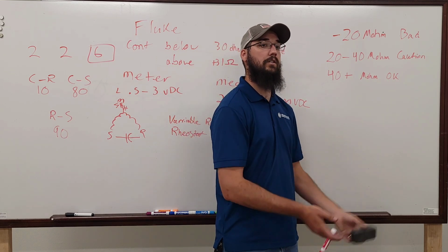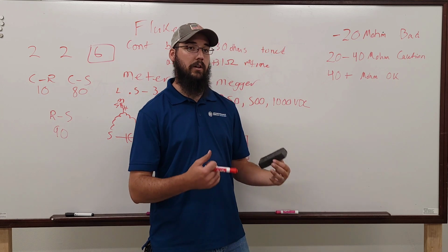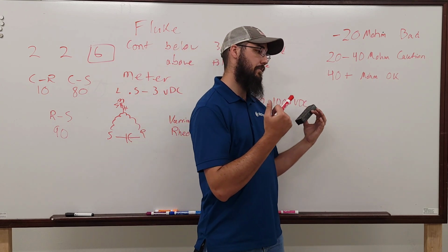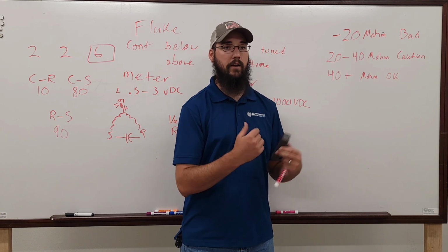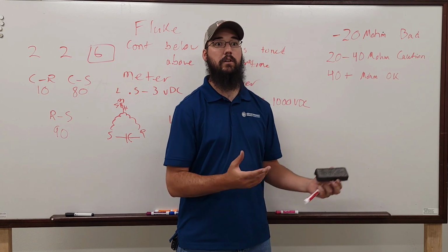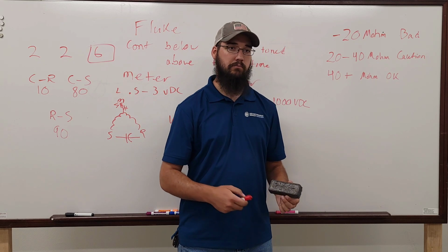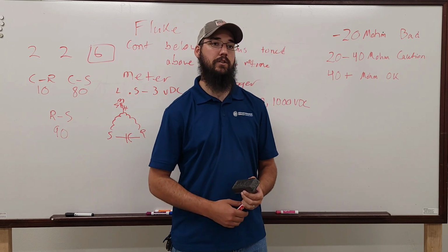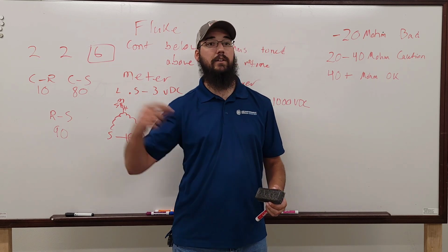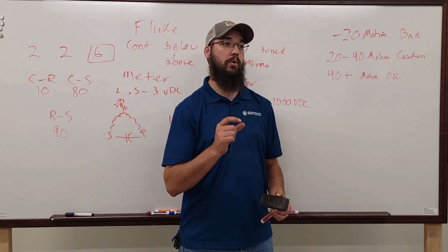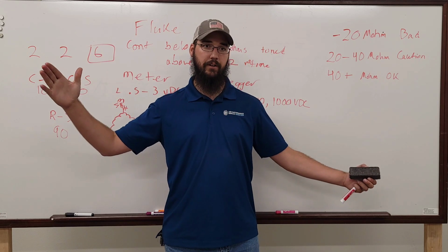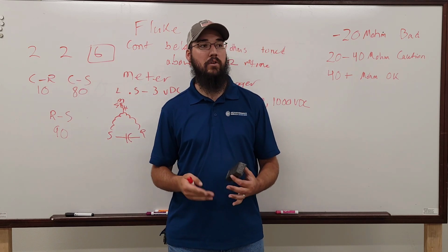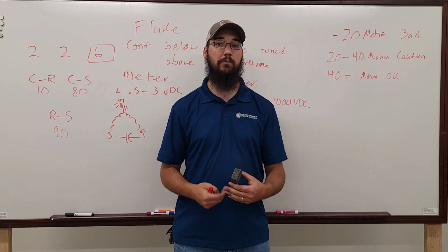We come in, this inspection, we've got on our inner and outer bearing 0.05 readings, okay? Extremely low, or 0.1. The next annual we did the next year, we're at 0.3. The next annual we did the next year, we're at 0.45. Trend here.